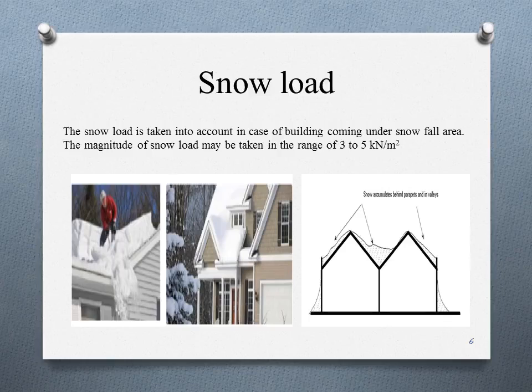Snow load. As you can see in the diagram, the load of the snow acts on the roof. The actual load due to snow will depend upon the shape of the roof as well as its capacity to retain the snow on the roof. The design of the roof should be such that it can bear the load due to snow. Mountainous regions in northern parts of India are subjected to snowfall. Load of snow may be taken as 2.5 kg per meter square per centimeter depth of snow.